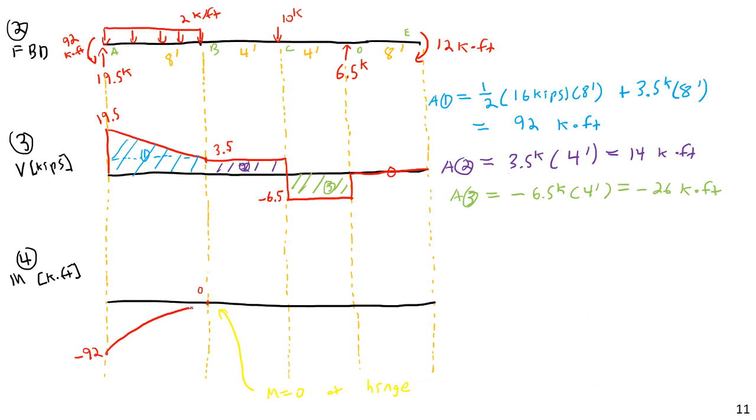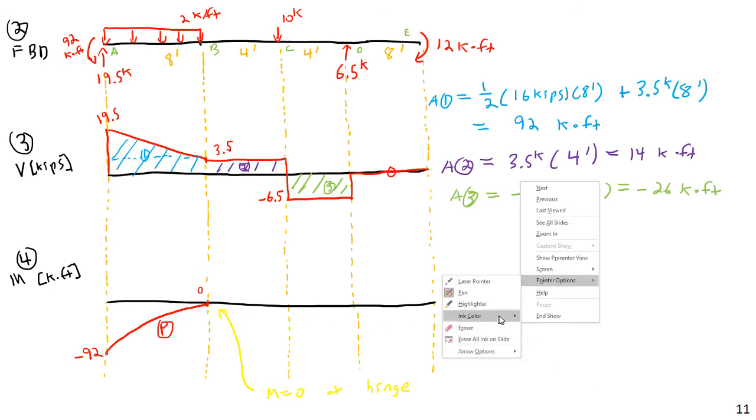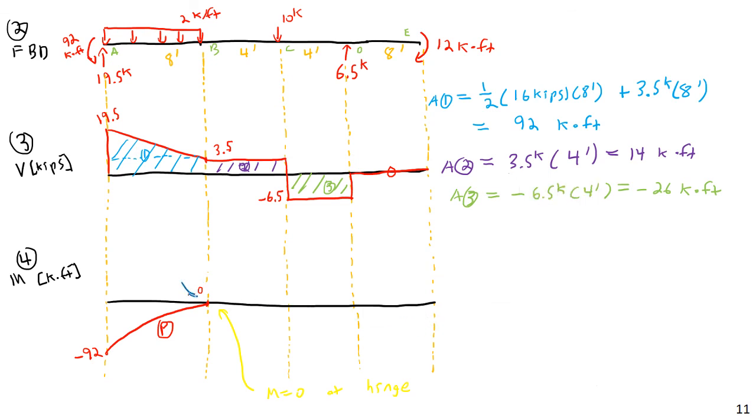So it should go something kind of like this. It doesn't actually equal 0, but it does become less steep as we go. It's sort of flattening out. And I'll go ahead and put a P here to indicate parabolic. And maybe I'll put a little note here just for us, showing that shear decreases, therefore slope of M shallower.